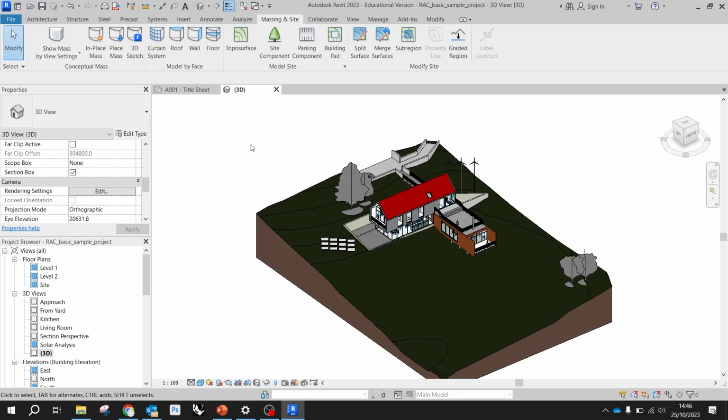If you want to turn that cube into an elongated column, you will need to extrude the top face, or scale it in one dimension, things like that. In Revit, you will have an element that is not just a cube, but is a column. So it carries certain properties, and as you have a list of information right here on the left for the views, you will have the same for pretty much every element you pick in Revit.